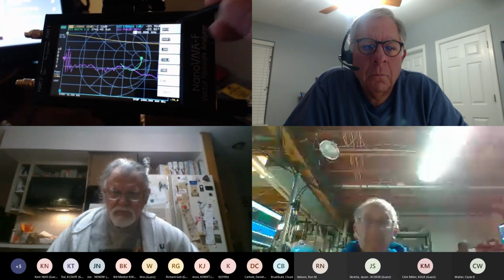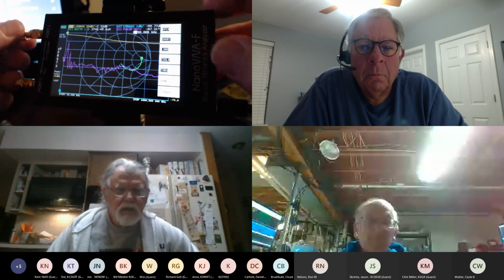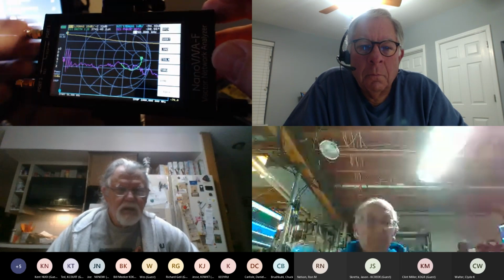Okay, great question, Jason. So we're going to do a quick calibration here. And as we step through each of these, it's going to prompt us for the next. So I'm going to look first of all for my open. In theory, we could just leave the connector open. In practice, we want to be consistent with our calibration plane. So I've got an SMA connector that is an open, and we'll hit the open. And it's that simple for the open.